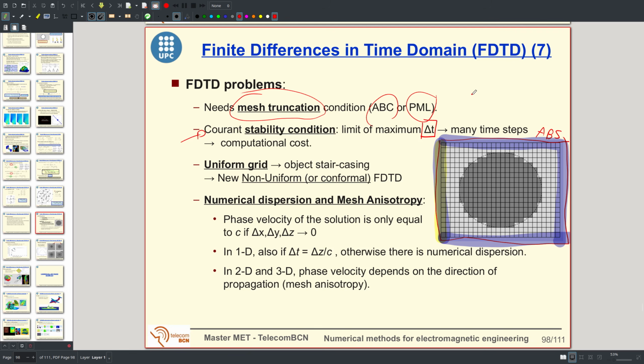This means that if we need to sample on a long frequency interval, because, for example, if we need a response in a high frequency range, or if we need a very fine sampling in frequency, for the Fourier transform we need a very long time interval.